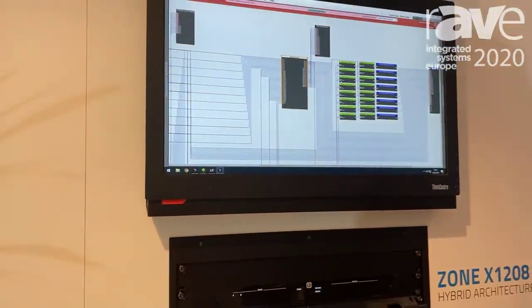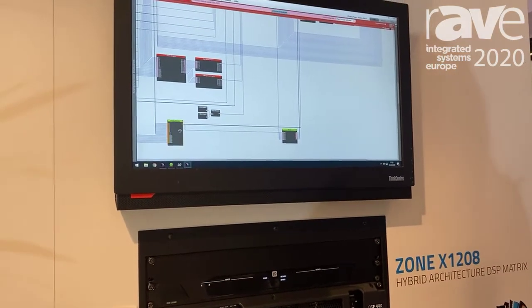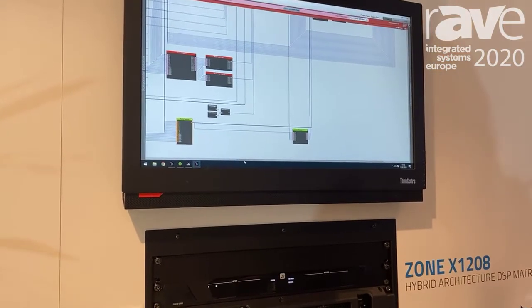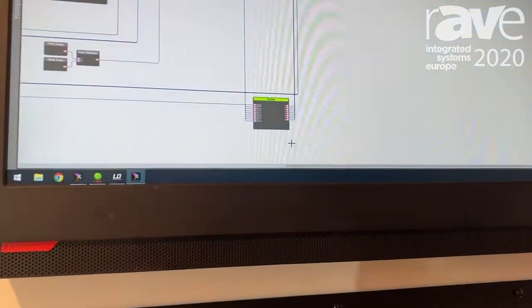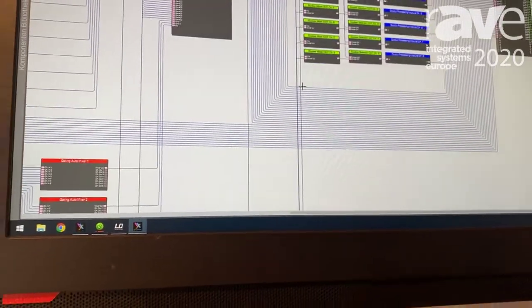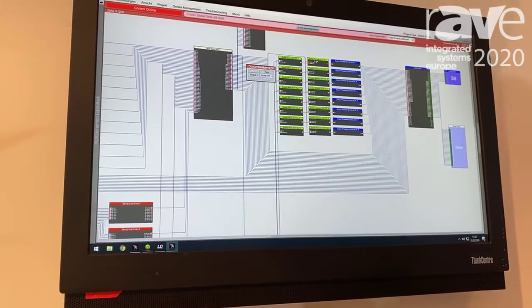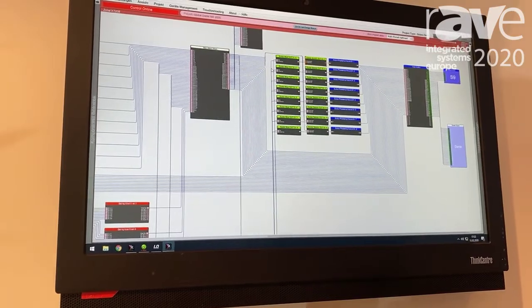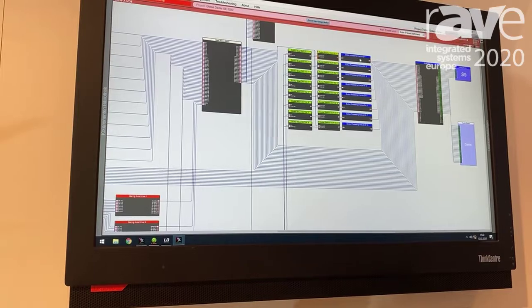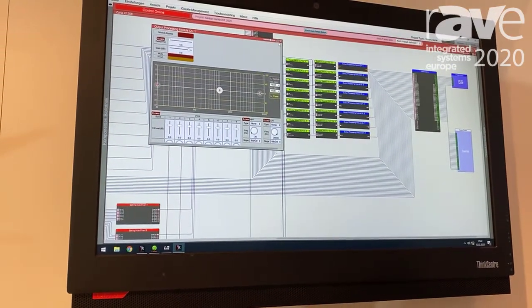One more thing we added to this design is a ducker module, so you can decide which of the input signals here is the priority source that ducks other sources, and we're ducking the outputs here. You can adjust the ducker actually, and once the signal gets out of the ducker, here you can decide simply if you want to use the signal that's ducked or the one that's not ducked, going directly to one of the outputs. And before that, we have a very powerful output processing module which offers, let me just maximize this.